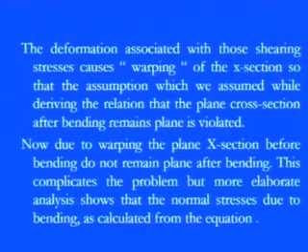Then we can't say that once you remove the load, all those fibers will return to their original form. It won't be possible. So this assumption is violated, that means the condition sigma by y equals M by I equals E by R is violated for this kind of case. Due to the warping, the plane cross section before bending does not remain plane after the bending, as we told you.